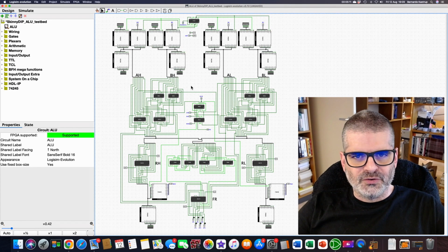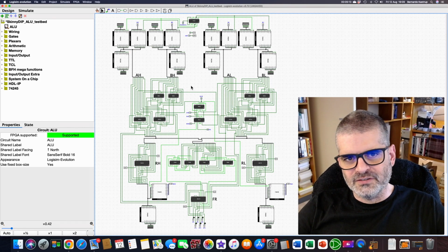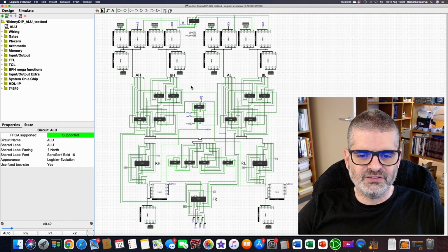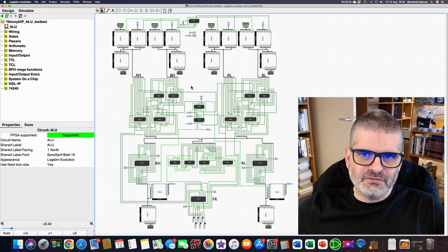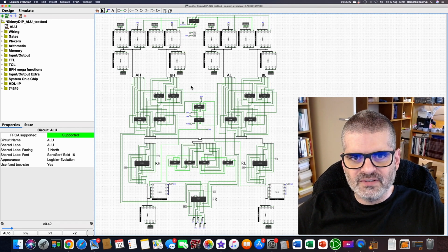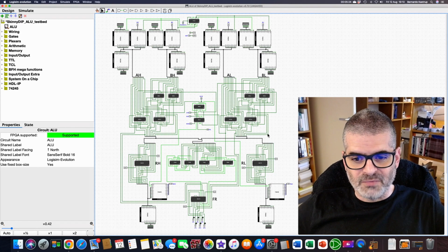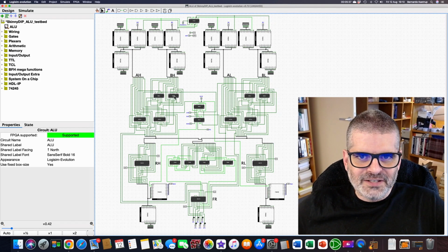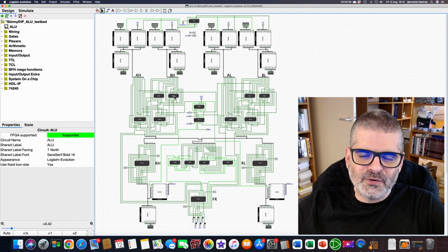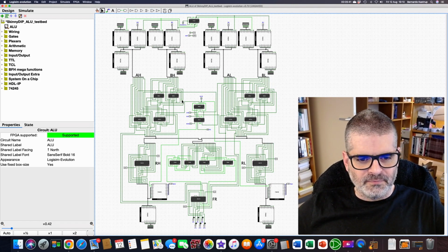Some of those models, you have to get a license for to use in a simulation. Most people would not get that license, so I was catering for what the hobbyist has available. But in this case, we have models for all these TTL chips, all these 74 logic chips. So there is no reason to do a breadboard prototype. And then you have to do it at the level of chips. That's where you want to run your simulation, because that's the only thing that is representative of the error-prone part. So that's the first question.